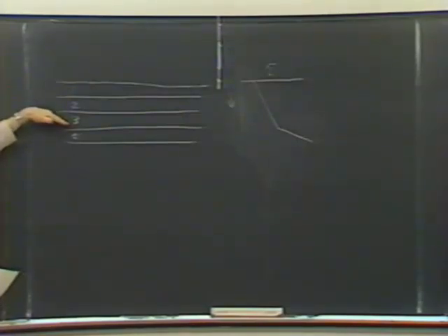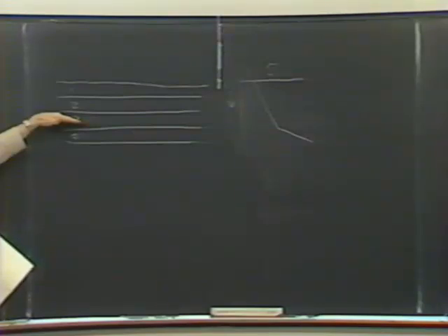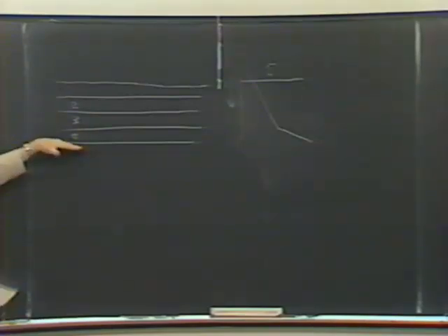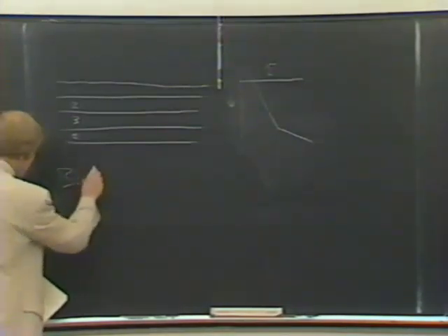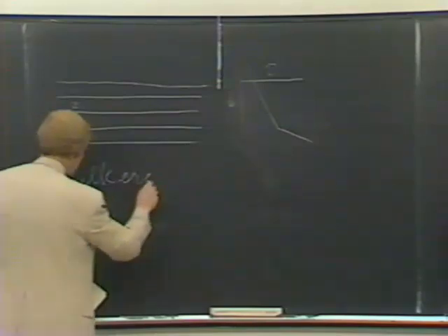But during the tidal cycle, the concentration of suspended material may change widely because right at slack water it settles out. Remember those plots, graphs of Savannah Harbor sediment? At slack water, the material really fell out of suspension and then was resuspended again. So it's necessary to keep track of that. And that's that bulk erosion, if you like, during a tidal cycle.